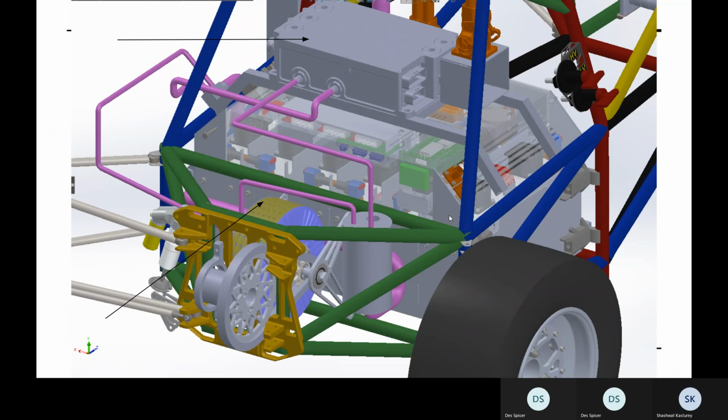So this is a fairly up-to-date diagram of our powertrain. I will go through just the basic parts here. We have the inverter at the very top, on top of a subframe. The subframe sits on top of the battery pack, which is massive. You can see it basically straps the whole car together. There are 6 battery modules, a load of cooling fans, and a load of control circuitry inside the battery pack. It functions as a structural member as well as the thing that stores all the energy.